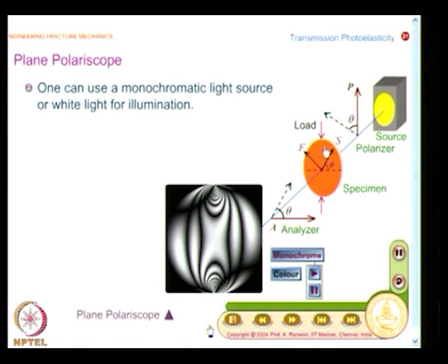And when the model allows plane polarized light as plane polarized light, as we have looked at in the wave plate. If the wave plate behaves as a full wave plate, then whatever light impinges on the model goes out unaltered. So, a plane polarized light incident on the model will come out as plane polarized light, which is a function of wavelength. The moment you say it behaves like a wave plate, you will also have to bring in the function of wavelength. That is the reason why we first look at only a monochromatic light source impinging on the model.